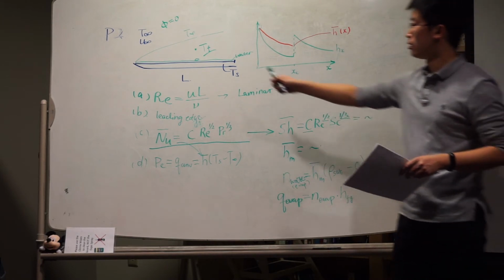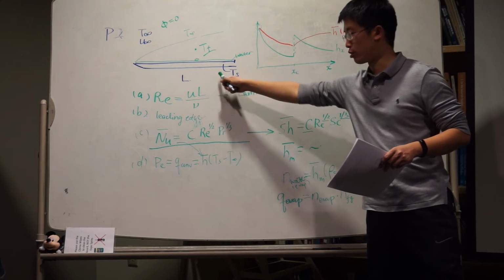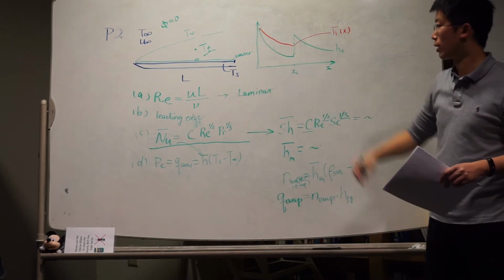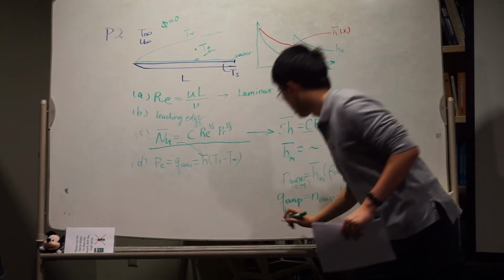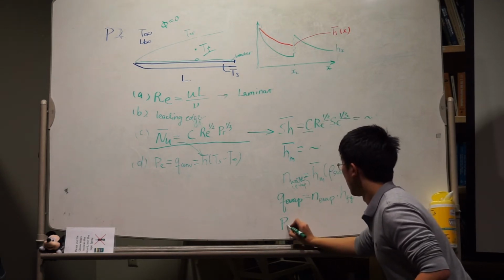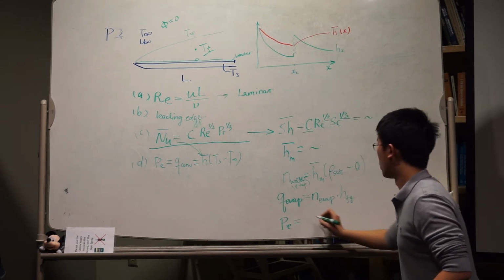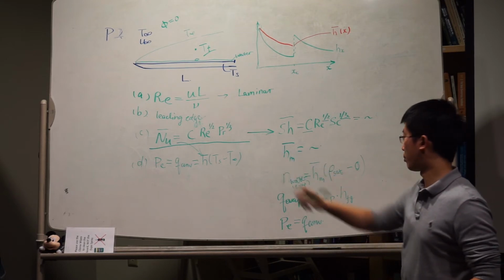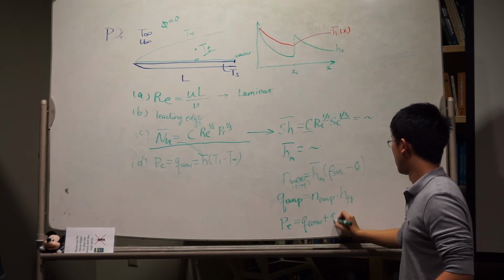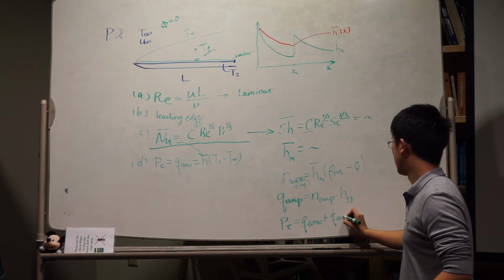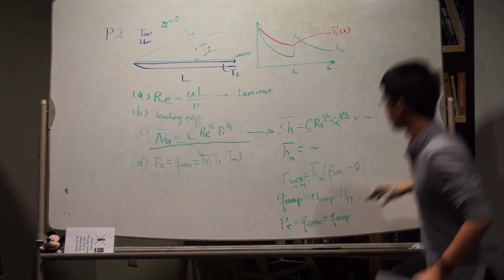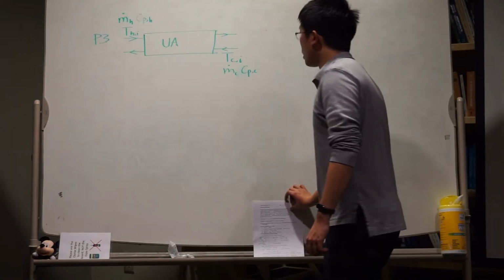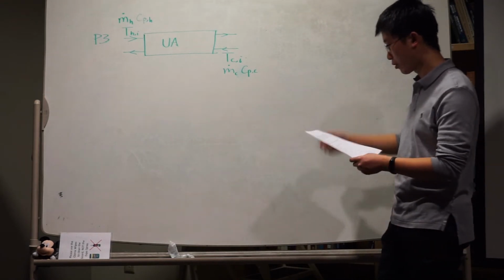And remember, the heat transfer still exists when we have the water there. So now this power, this electrical heating power, will be the convection we calculated in part 1, plus the heat taken away by evaporation we just calculated here. Okay, now let's look at problem 3.